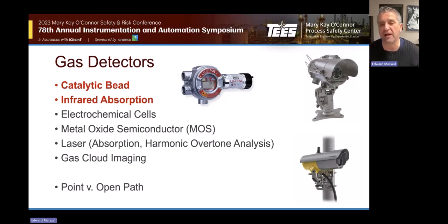So if you have detectors that are trying to detect hydrogen sulfide, you are going to use hydrogen sulfide as your calibration gas. It's not like we are like, well, I'm going to calibrate based on ammonia, but I'm trying to detect H2S. Well, it just doesn't work that way, whereas it is very common for the flammable detectors.